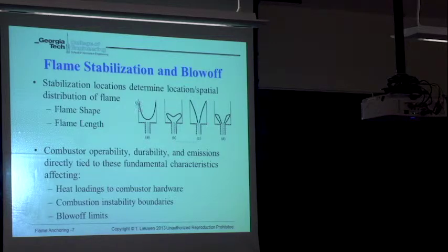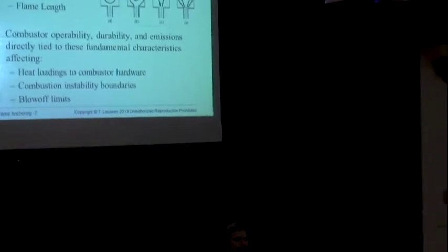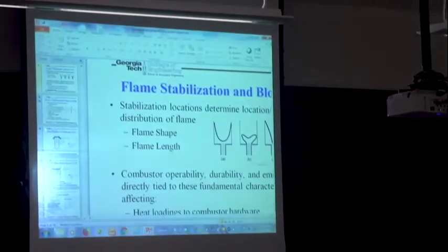What I want to chat about now is, presumably if we have a swirling flow, we may have vortex breakdown, and you can have an interior stagnation point. So the flow could be decelerating, and I can have the conditions where a flame can stabilize aerodynamically. So let's just chat about that for a couple minutes.